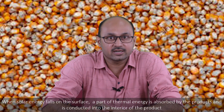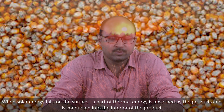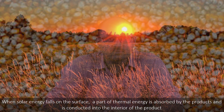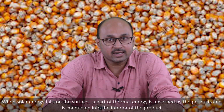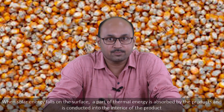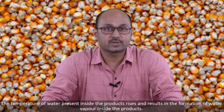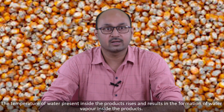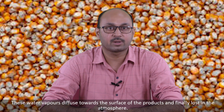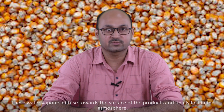When this process is going on, a part of thermal energy is absorbed by the product and is conducted into the interior of the product, because you know that evaporation always takes place from the surface. The temperature of water present inside the product rises and results in the formation of water vapor inside the product. These water vapors diffuse towards the surface of the product and are finally lost in the atmosphere.